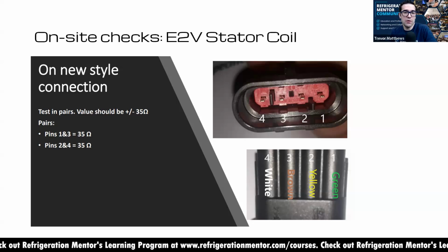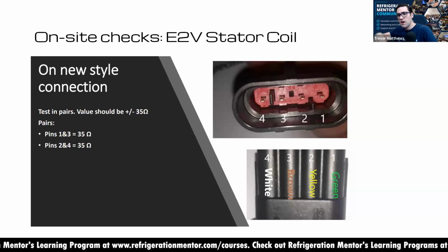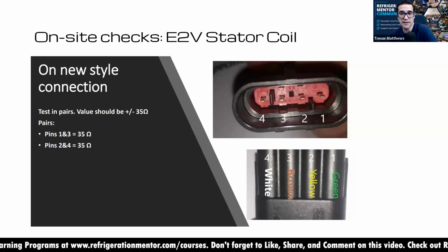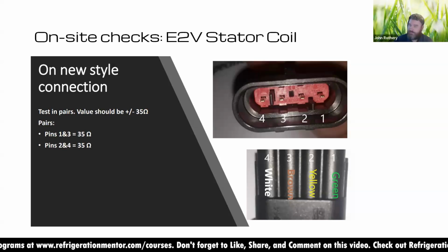And one thing too, if you work in a supermarket, there are meat rooms and stuff, and they're spraying down everything, all the walls, and water splashes up and could fill up either the transducers or the electronic valve cable. One contractor about 8 or 9 years ago said, Trevor, we use heat shrink. All their electronic valves in the wet, moist areas, they pull a big piece of heat shrink over it, so any water that gets onto it doesn't get into the valve itself. It reduces some rusting and water getting into the valve. Yeah, stop the ingress.